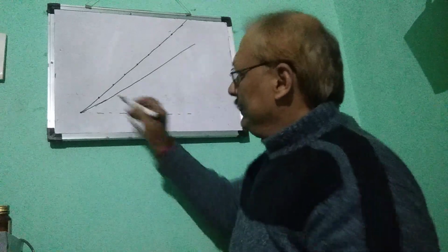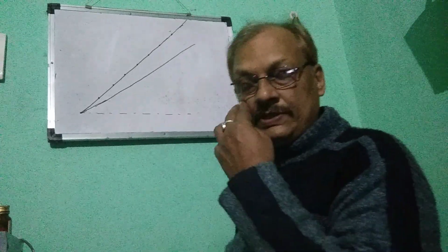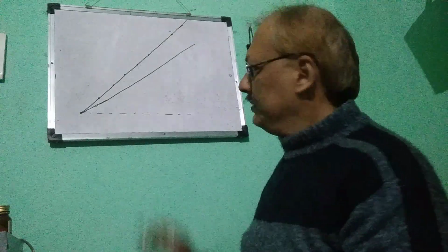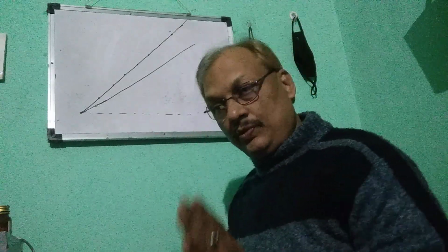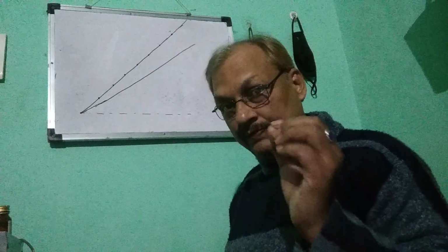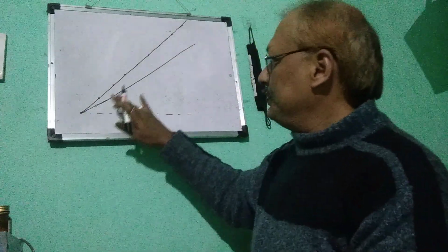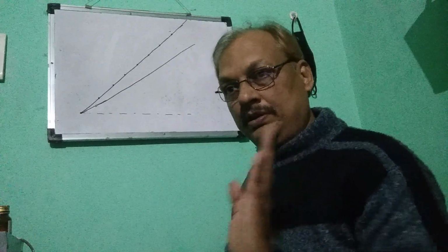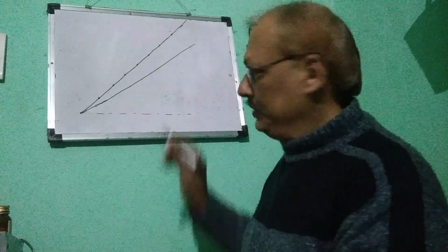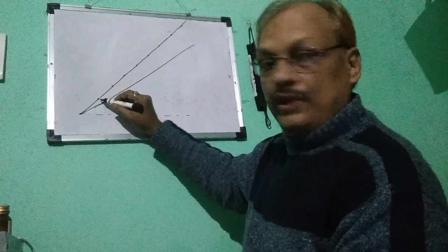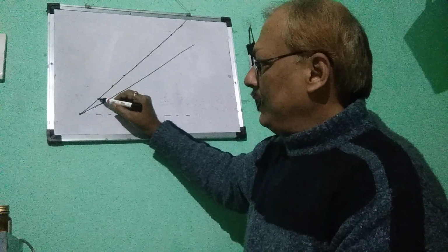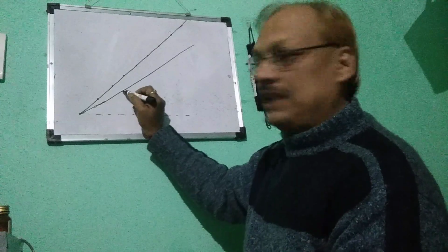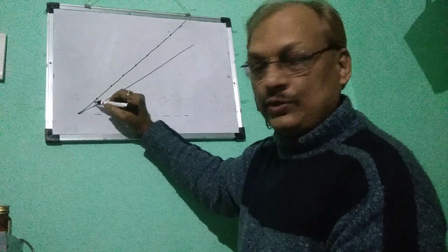So here also you will get 7 graduations in the isometric scale. With 10 graduations, you will get 10 graduations, and any one graduation you have to divide into 10 parts. That is for mm. This is suppose a centimeter, so for mm you have to divide any one graduation into 10 parts, that I will tell you. Now you have to do nothing, just from each and every point draw verticals which will cut this line, and those will be isometric lines.